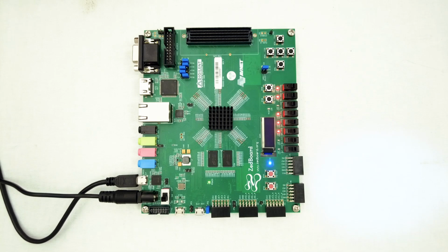So this is all about FSM. Mainly we have implemented sequence detectors for 100 and overlapping 10101, and this is for a Moore machine, in which the output depends only upon the current state. So this is all about this demo, in which we have implemented some FSMs, right? The first is the sequence detector detecting the sequence 100. The second is the overlapping 0101. The third, we have implemented the Moore machine in which the state changes with the clock.